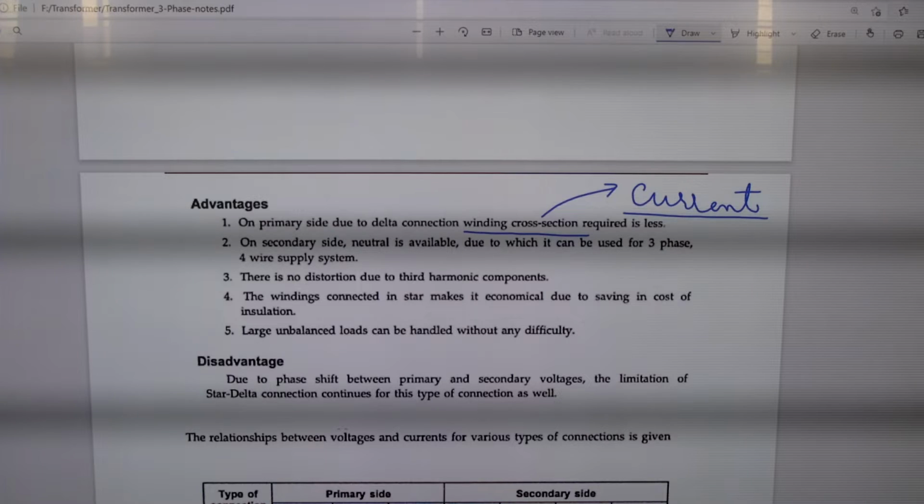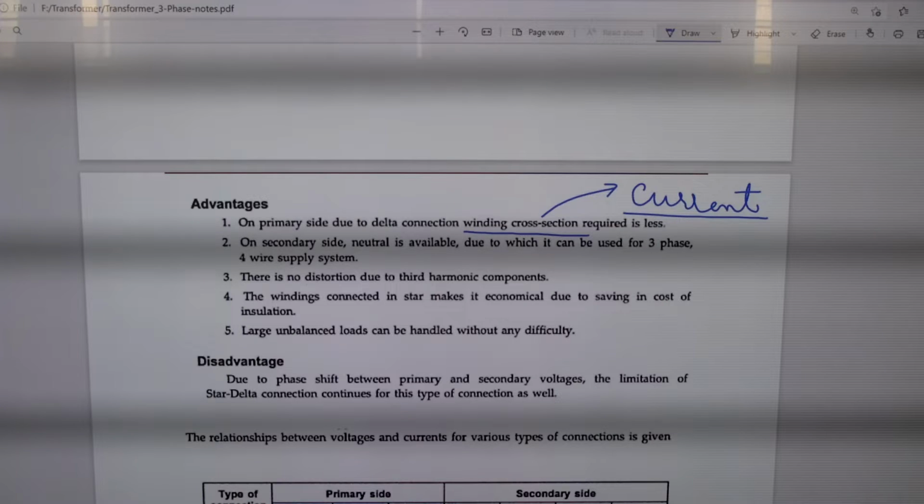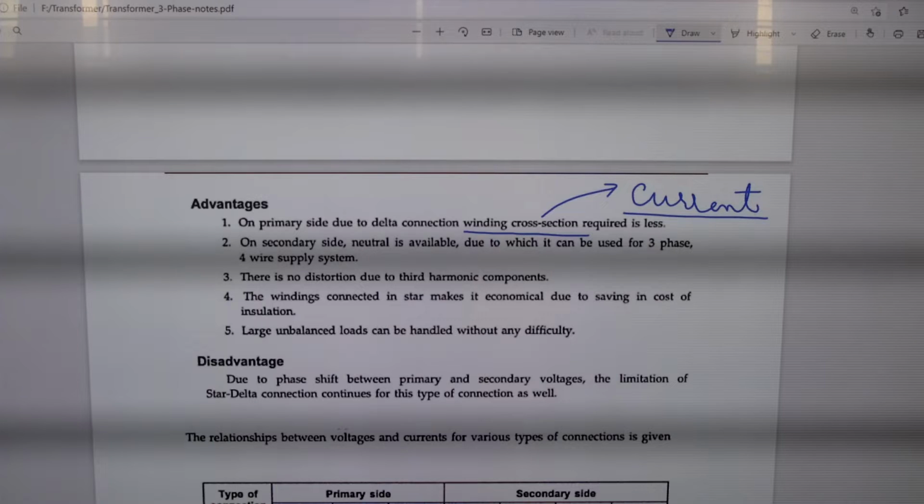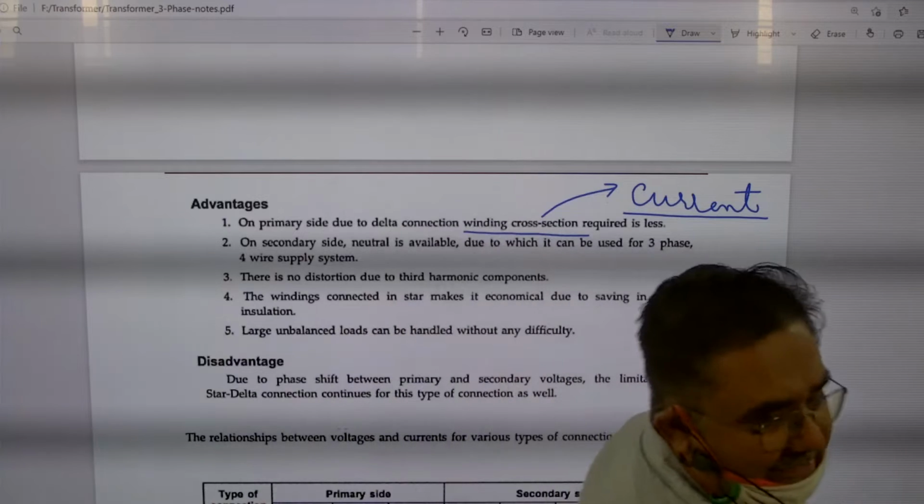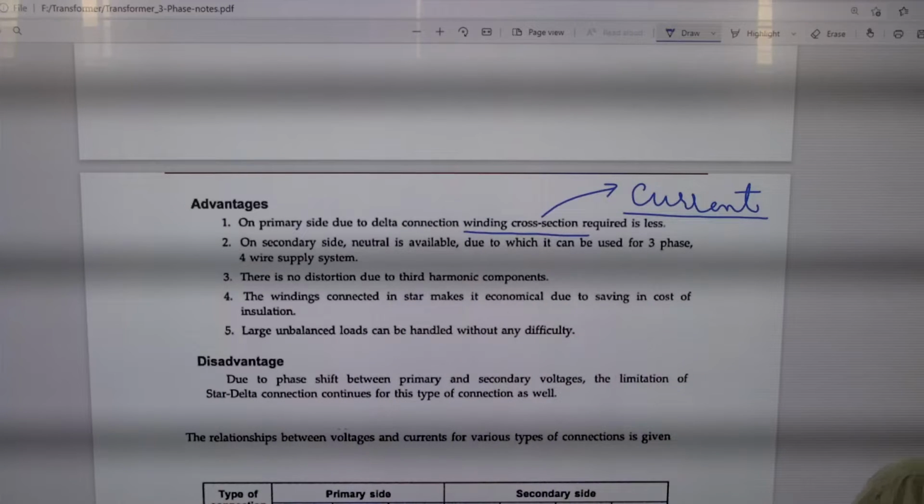And for the one coming from your live wire, that is the distribution pole up to your meter, we generally go for 8 mm or 10 mm square. You got my point? Okay. So how is this mm increasing? What factor is increasing it? Current. When I say mm square, what is mm square basically? It is the cross section of the wire.